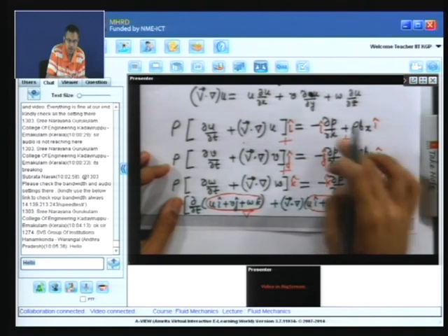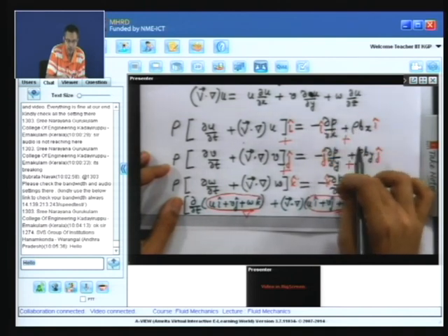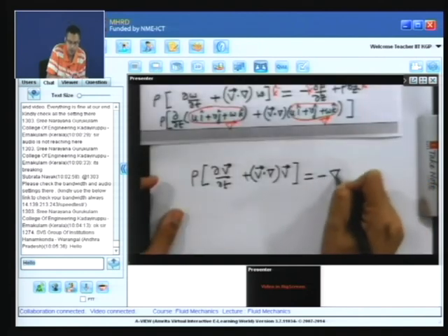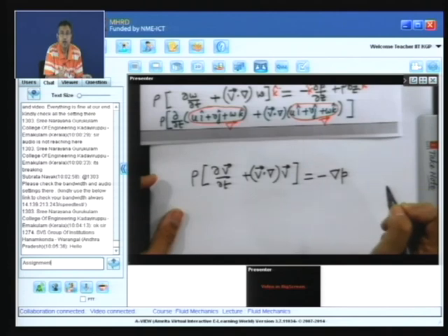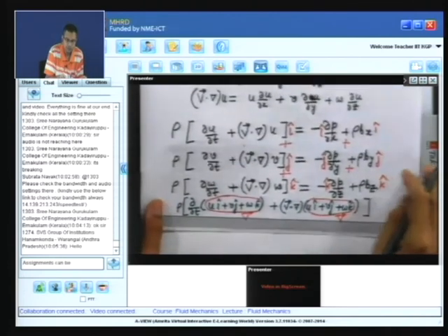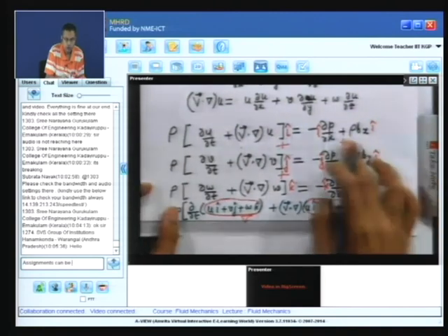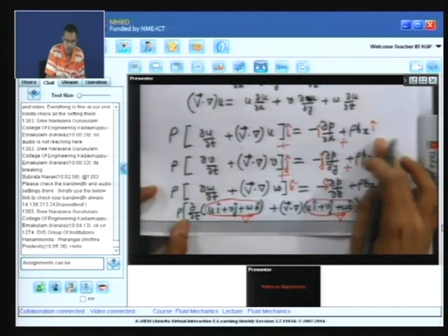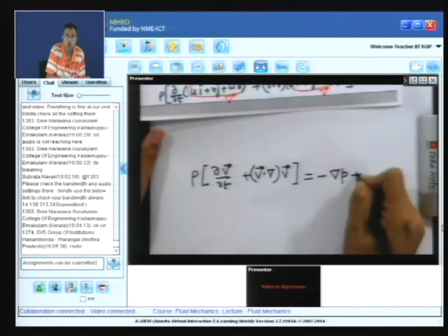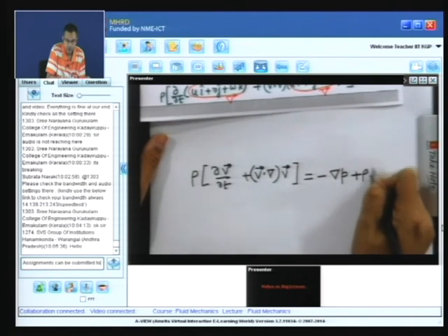So minus i del x plus j del y and k del z, it effectively becomes minus grad p, and the last term rho bx i plus rho by j plus rho bz k becomes plus rho into the vector b.